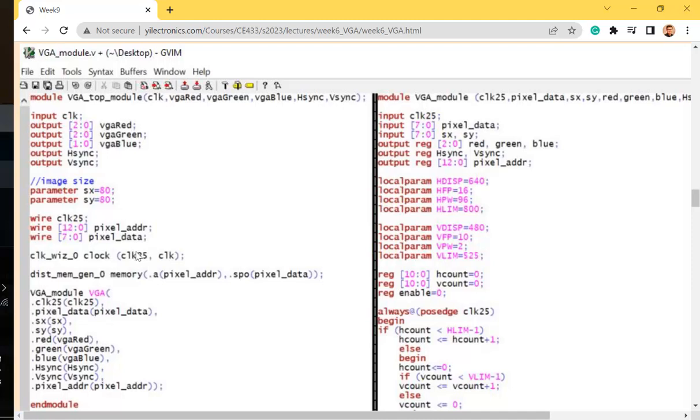In the Verilog file, you could do the dot, whatever they're called, clock out 1 or something. I just didn't write it down, right? But these signals, if you use the traditional way, should be put into the parentheses, with a dot something parentheses clock 25 and dot something parentheses clock, right?